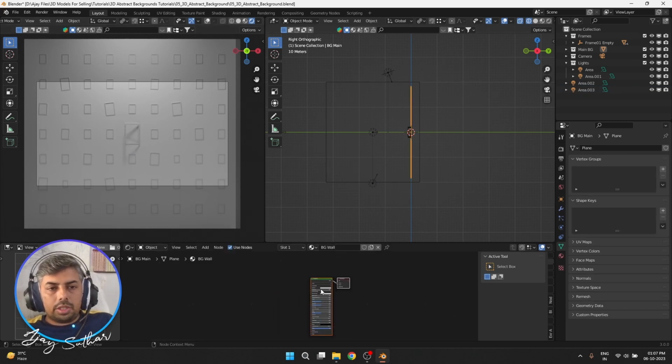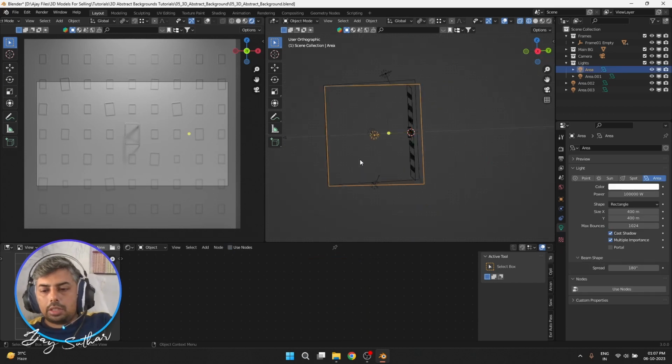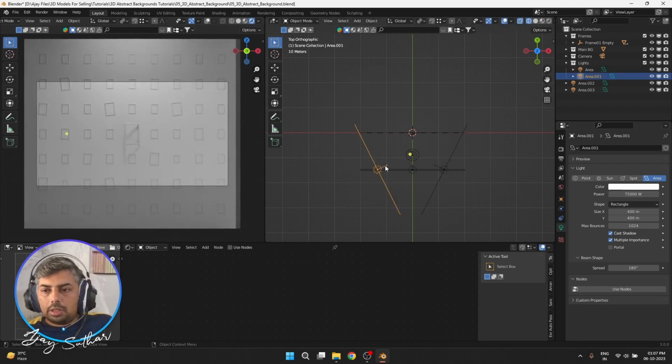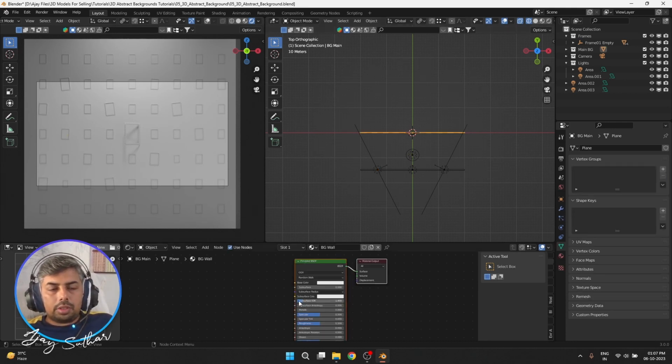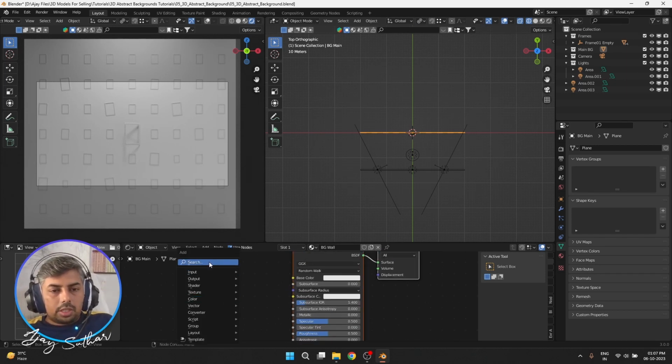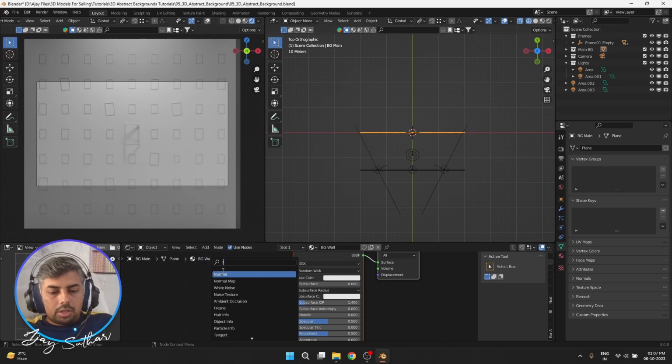So first of all, for the BG wall, let's change the intensity. Let's push it to 15. I want a good bright light. 20. This is 75, so make it 10. Okay, and this is obviously enough. So now I will use texture for this wall. That is what we will do. Concrete wall. Let's create a concrete wall. So I'll say noise texture.